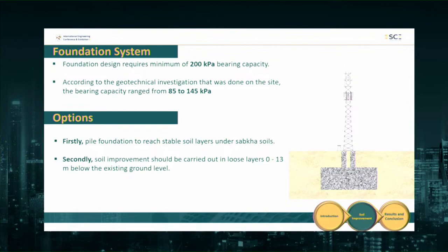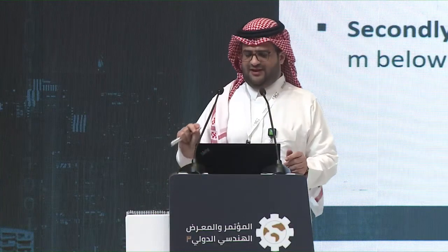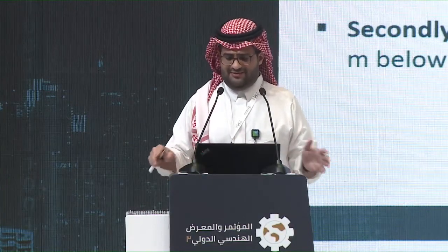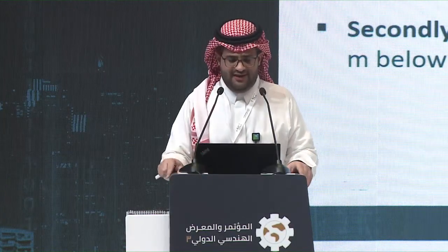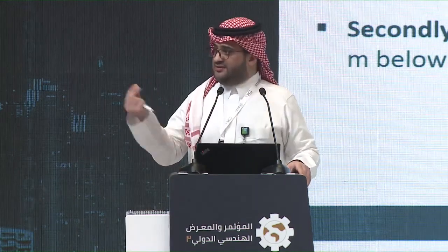Going to the foundation system, our geotechnical engineer has specified a minimum of 200 kilopascal bearing capacity to carry the raft foundation. However, in the existing condition, we have 85 to 145 kilopascal bearing capacity. What are the options that we had?